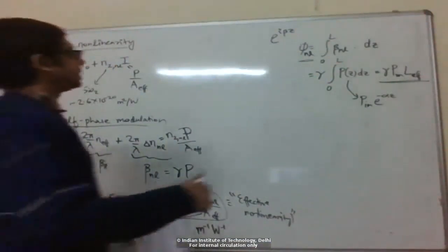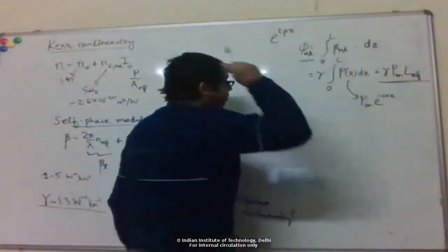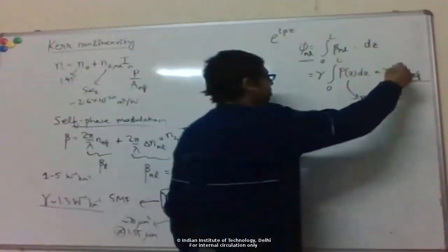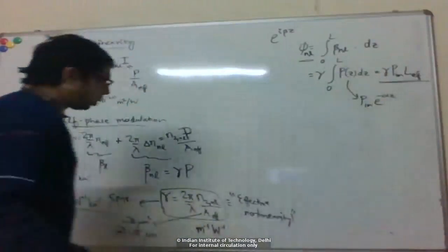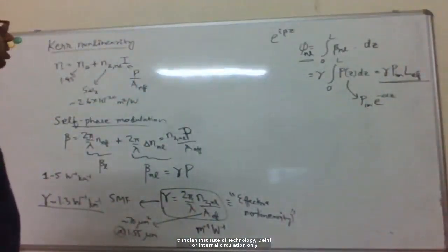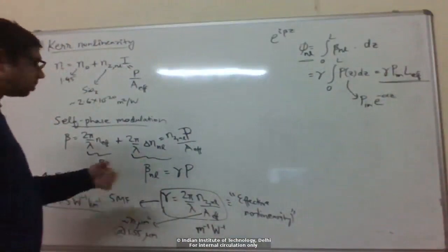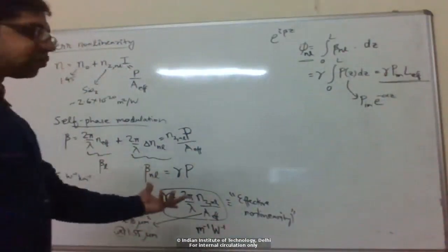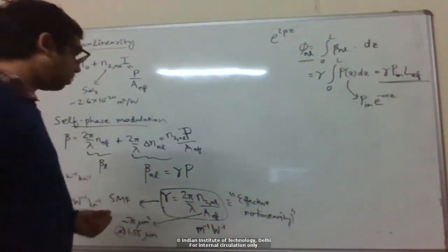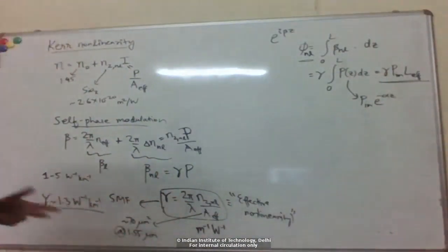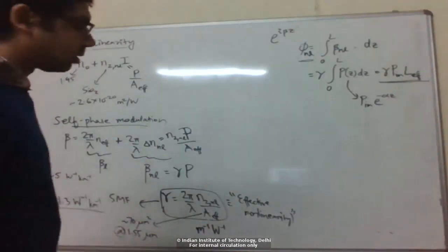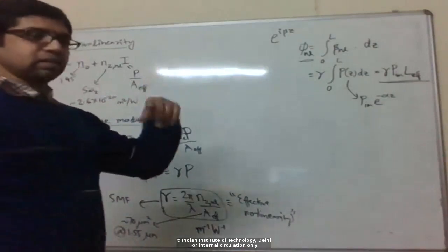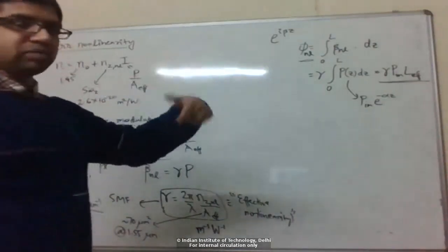So you can see there is an additional phase here, which depends on this effective nonlinearity, input power, and so on. You can immediately see that, for example, if we do some modulation which is based on the phase, like phase shift keying, or even frequency shift keying, so you have these schemes like BPSK, QPSK, where we encode information in the phase, for example, 0 phase is bit 0, pi phase is bit 1.